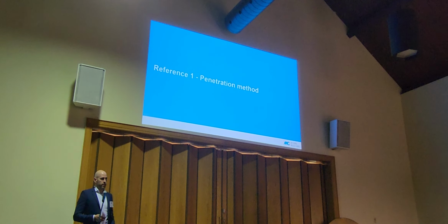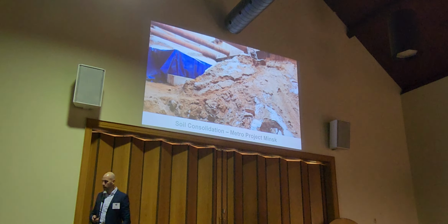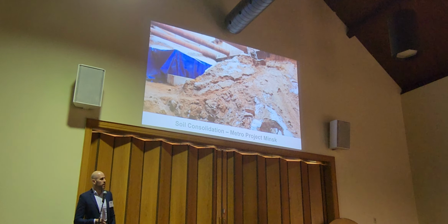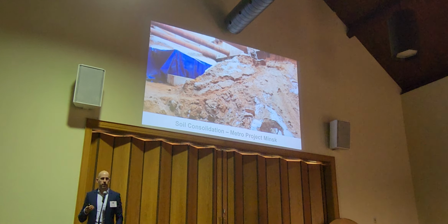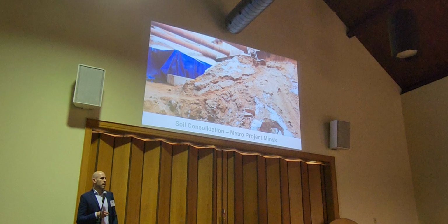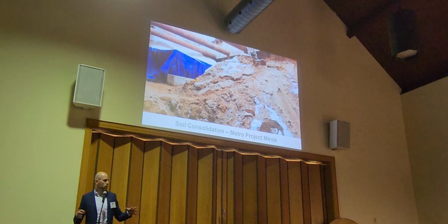First of all, the penetration method. This is, let's say, the easier injection job. But easy doesn't mean that it's not challenging for the equipment, for the material, and also for the application team. Here is one project which is from Belarus, and this was a soil consolidation of a very, very porous soil without fine content. So they had tried to build up a new pedestrian tunnel for this metro project, and therefore they wanted to stabilize the soil.